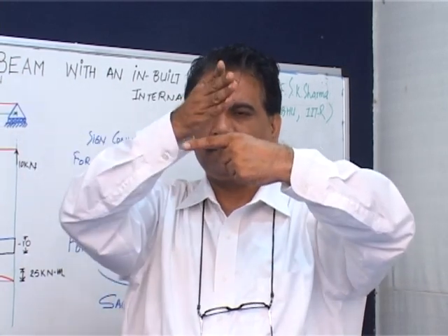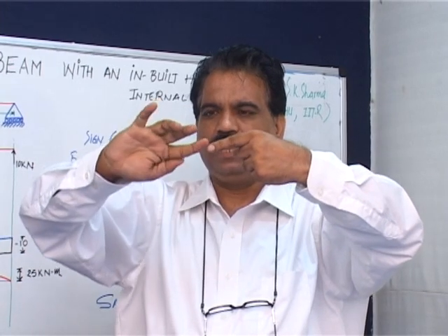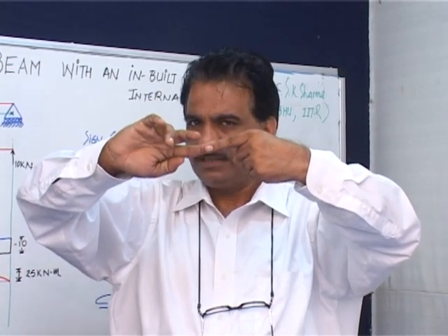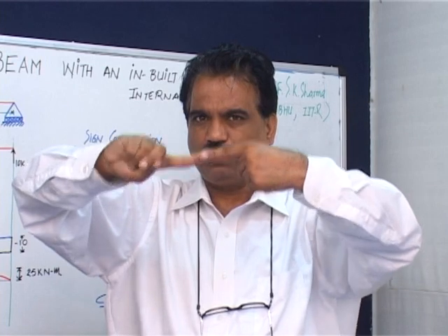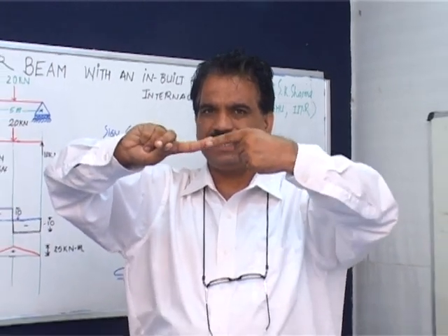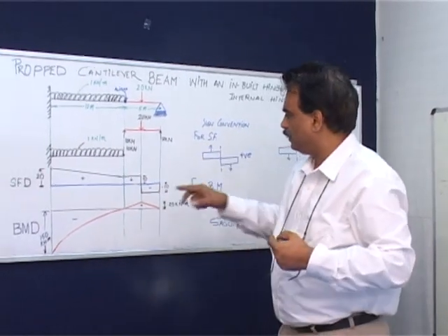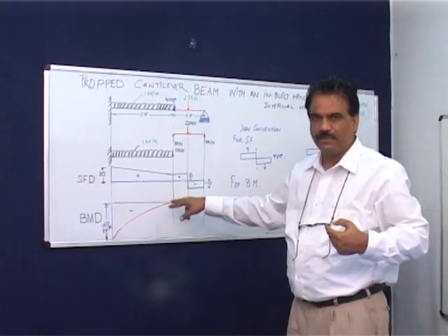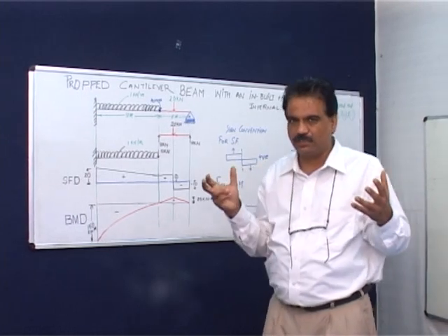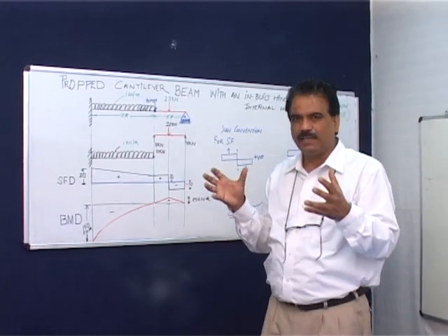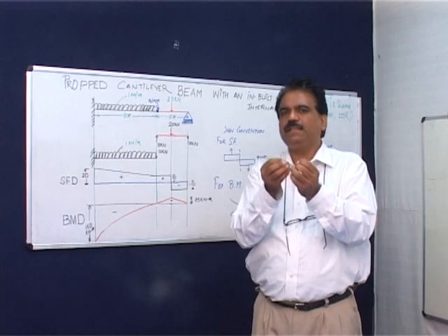Now you have a cantilever support here, and you have a roller support here, and this does not move down. It can only just twist like that, passing a moment. It will not resist a moment. So ultimately, in fact, the bending moment value at this point is going to be 0. That's just a foregone conclusion. But how do we analyze this beam? Some simple techniques are used.